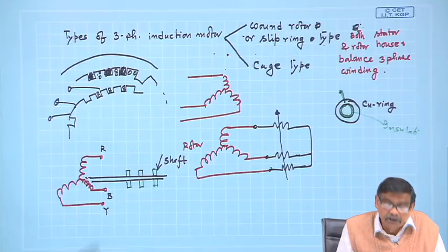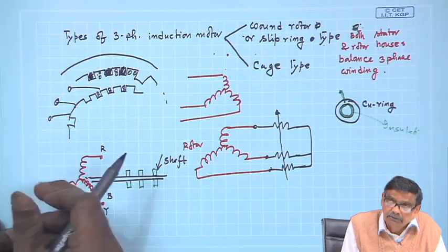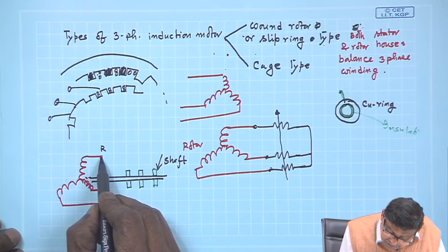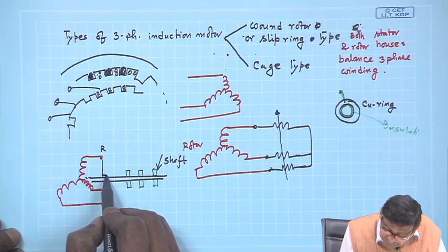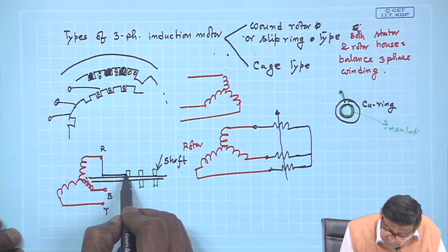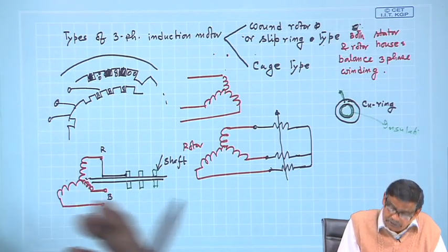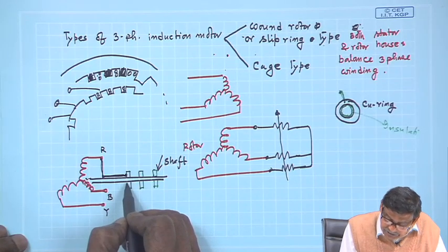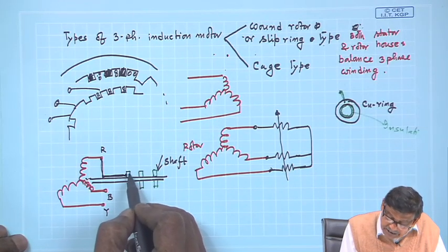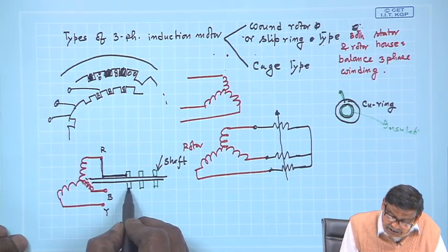Now, you do a little bit of wiring. Wiring means this R phase, Y phase and B phase, they will be moving, no, as the rotor moves. What you do? You take a wire, and once again all along the track you take this wire and terminate this R to this copper strip. You either screw it or weld it, in some convenient way. So that no matter where the rotor is, this copper ring itself is the R terminal.